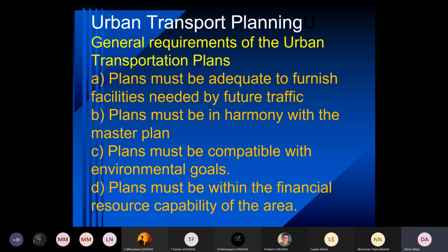So ideal situation, you would love to have 3 lanes in each direction, low commercial vehicles, no heavies on the road, okay? Good sight distance, flat curves, okay? Large radius of curvature, good super elevation, but it's not always possible. So one has to look at the economic factor, one has to look at the terrain, and so forth.